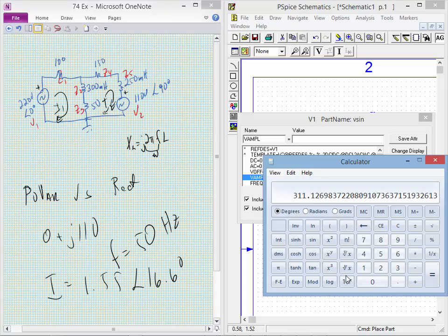Peak. Right there. Because, again, I'm assuming this has been covered in your class, when you look at AC, what comes out of the mains, when you see 220 volts, that's the RMS value. And in reality, what we would be seeing on an oscilloscope is the peak value. In this case, 220 volts is going to be about 622 volts peak to peak. So we should put in 311 there.